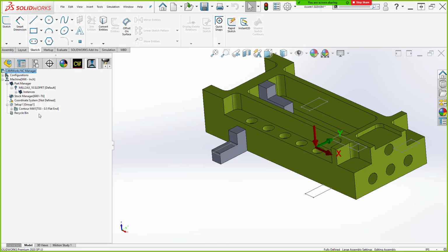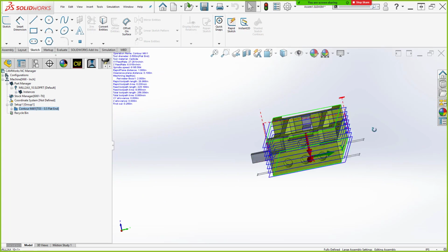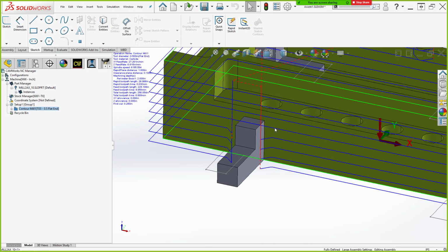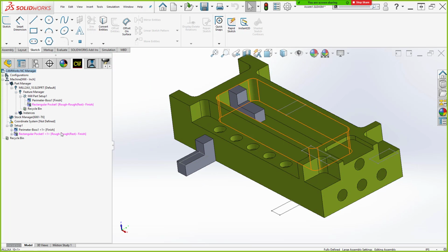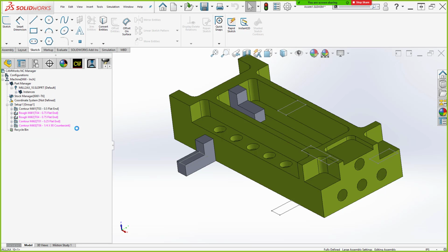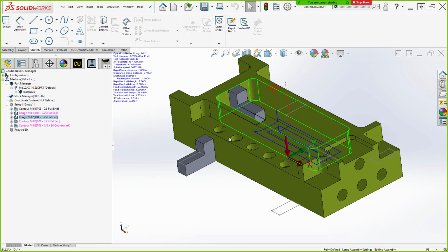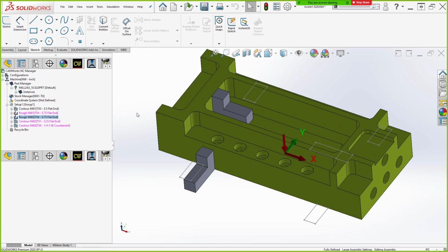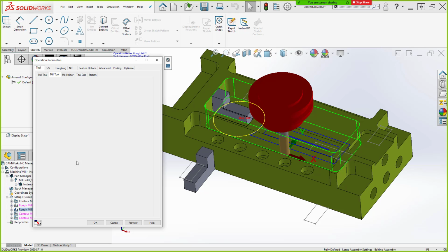Obviously, it wants to regenerate my toolpath, right? And you're seeing, oh, that's right, I only have the clamp on the one side. But you're seeing some intelligent motion around that clamp, right? Looking internally here at this pocket, if we were to program a rough mill, let's just generate operation plan out for that rectangular pocket, and then let's just generate a rough mill operation. Tool's a little too big to see what it's really doing as it interacts with that clamp. Let's go in and change that so that we can see a little bit more clearly how it behaves with respect to the fixture.